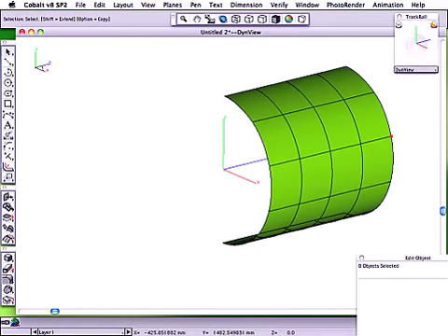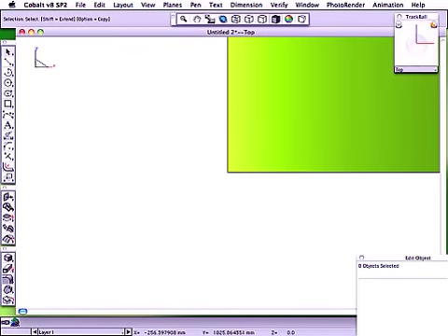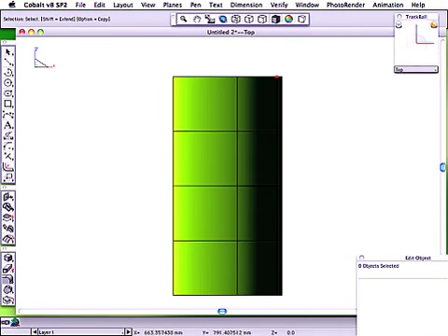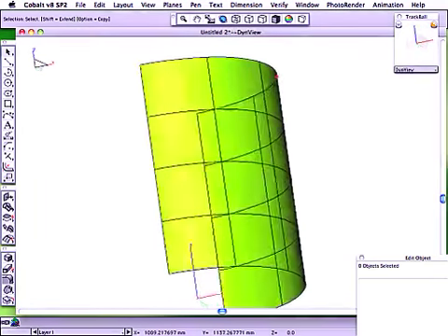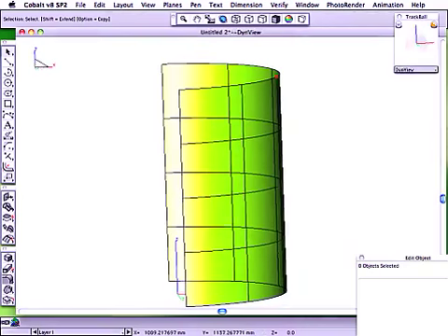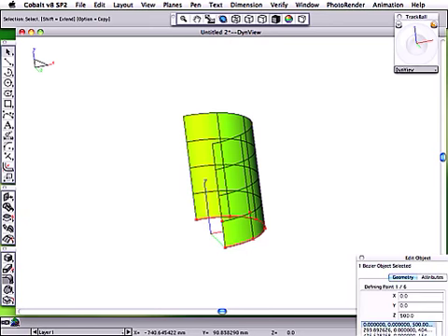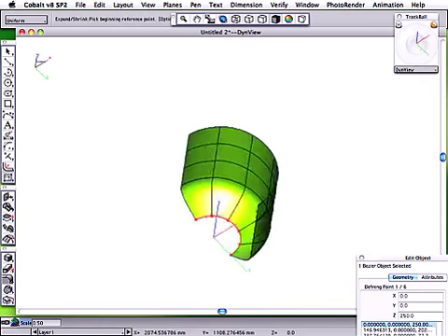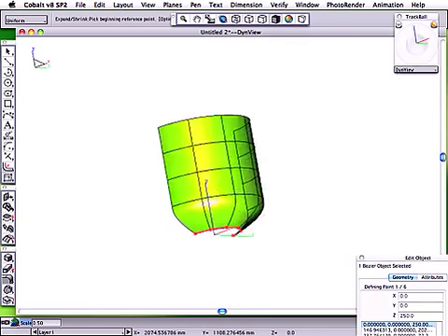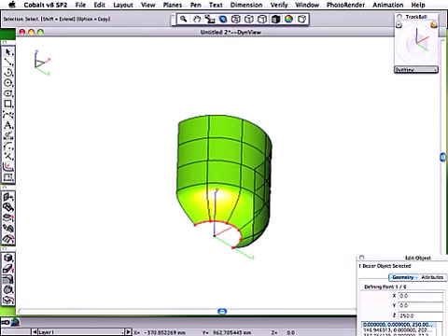If I pull on a point, the spline goes with it, the surface goes with it. Select all or a bunch of points, except for those ones. Now use the scale tool, and I'll scale those points from the origin, 50%. Points move and the surface moves with it.